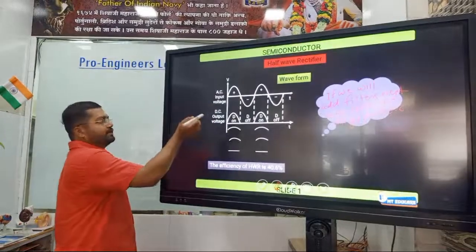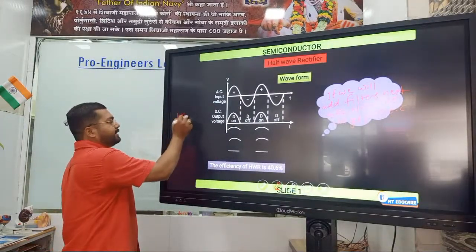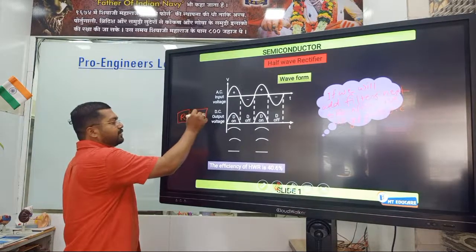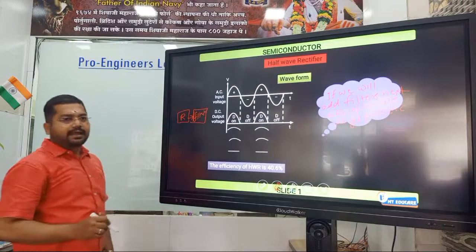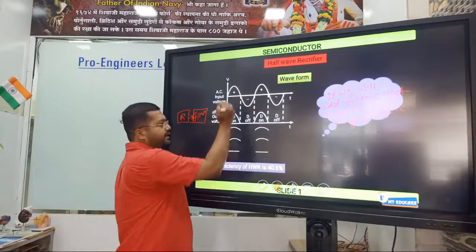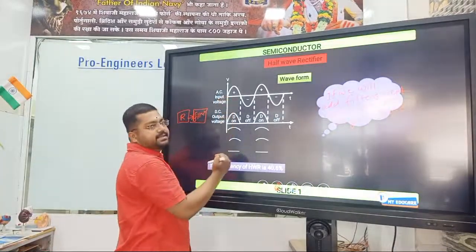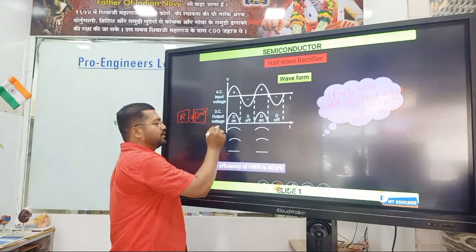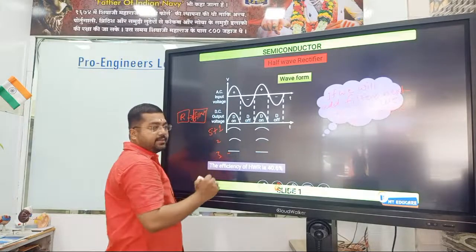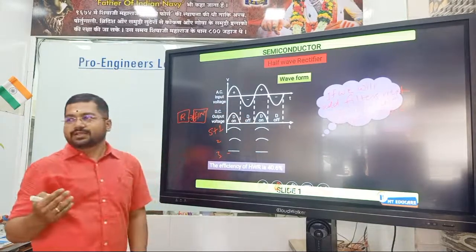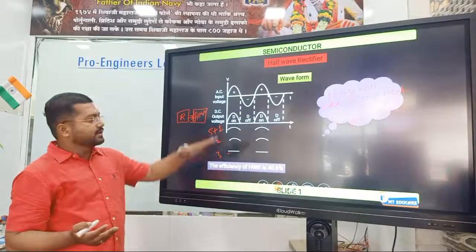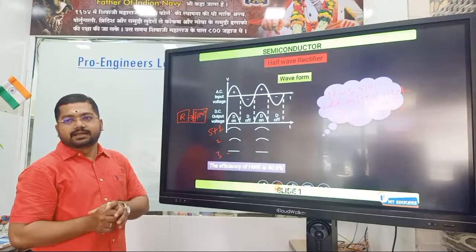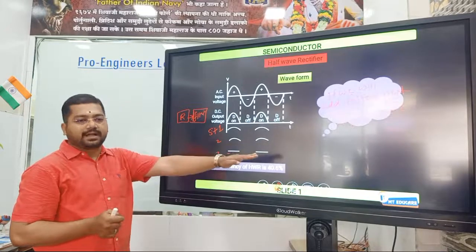It means whatever rectifier circuit we have seen just now, if we connect filters next to it, then the pulsating DC signal is converted to a straight line. It means this is stage 1, this is stage 2, stage 3. If you increase the number of filter stages, it will certainly rectify it and give you the final DC signal, a straight constant line.